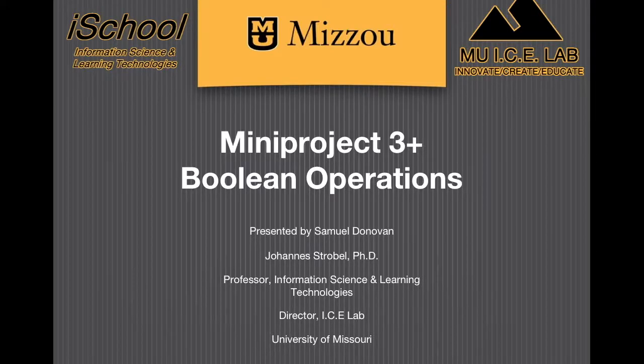Today we'll be using Boolean operations on two models. Boolean operations involve merging two objects and either combining them together, subtracting one from the other, or creating a new object from the intersecting portions of the original objects. Boolean operations do have niche uses, but when the certain use is desired, they are very effective.